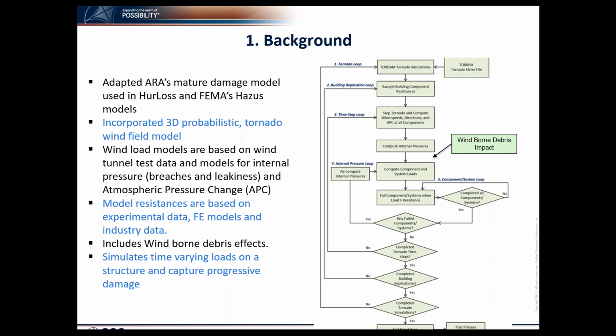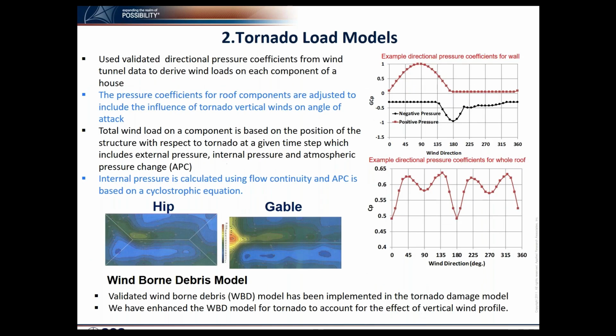So it's basically a load and resistance model. The loads are basically based on wind tunnel data, and the resistances come from the experimental results, finite element modeling, and some industry data. It also includes the windborne debris effect. Since it's a time stepping model, it simulates the time varying loads on the structure or building, and then captures progressive damage along the way.